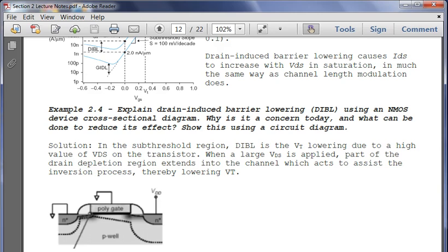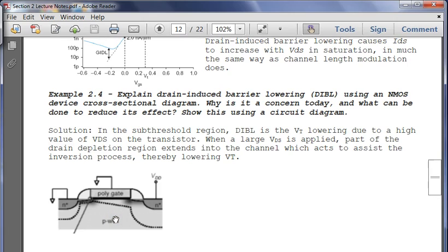When you're creating this difference at the well here, you're affecting the ability to actually create the inversion region versus being accurate. So if you lower the body, that creates more capacitance here. So you actually may run faster, but you have to worry about accuracy. If you put a positive voltage on the body, what ends up happening is that it's a little harder. It's harder to create the charge, but once you do, it's actually much more accurate and consumes less power.